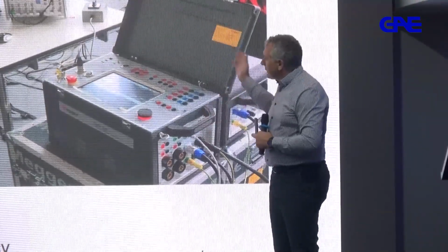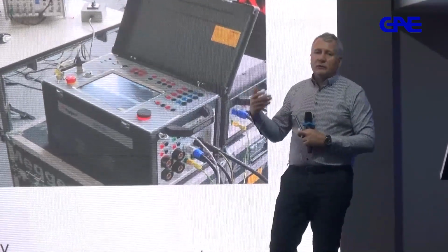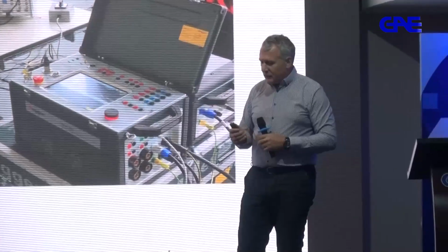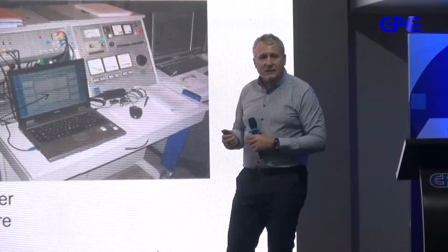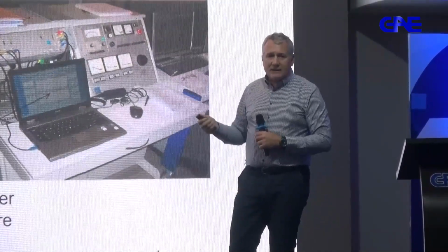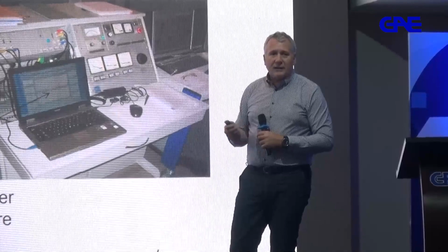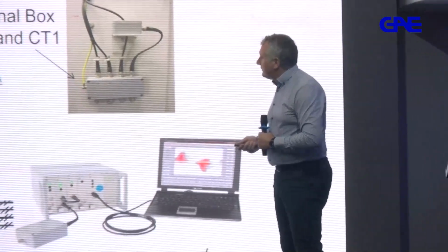And then once you power the test object, which is the transformer, you're going to carry out exactly the measurements that you saw in this particular setup. So powering the test object is another subject of our conversation, and that has to be done in a filtered manner, in a PD-free manner.